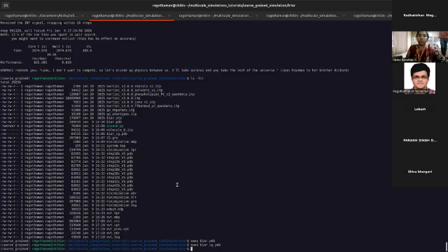Okay, so this is the data we have till now. You can just proceed with NPT, where you'll be using pressure coupling, and in case of the MD production run, we can run it for a longer duration. The same procedure will be repeated. These kinds of files will be generated for NPT as well as MD simulations, and we'll be analyzing the data with the MD output. So these are equilibration steps.